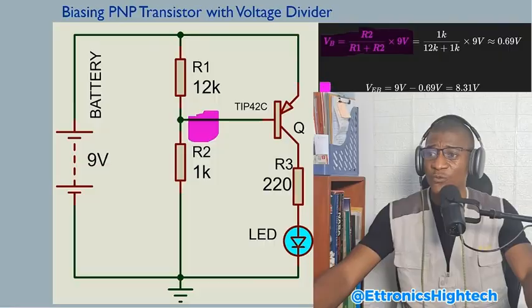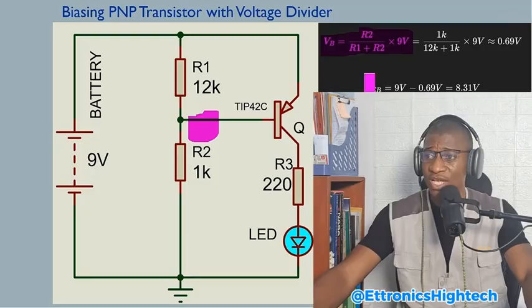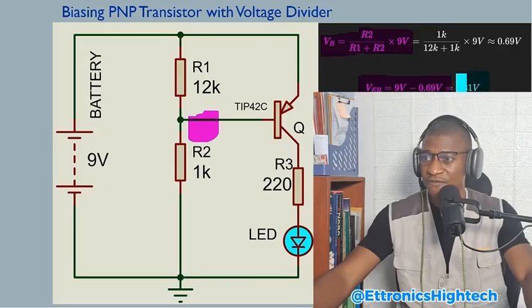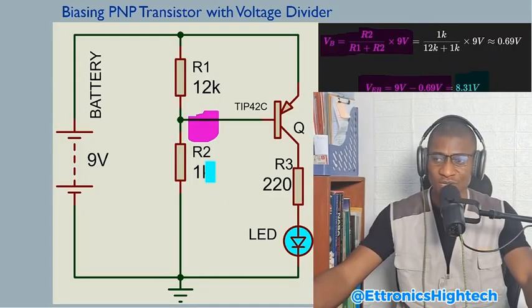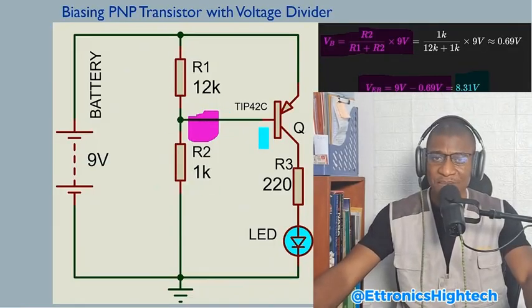So if we take into consideration the voltage at the emitter, which is 9 volts connected to this emitter, and we subtract that 0.69 from 9 volts, we will have 8.31 volts. And this 8.31 volts is enough to bias our transistor to saturation. And that is how we were able to use this voltage divider network to bias our PNP transistor.